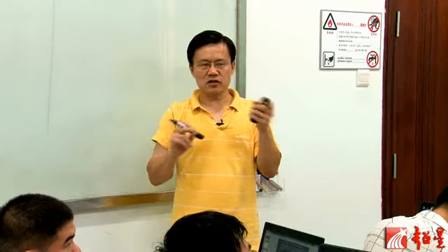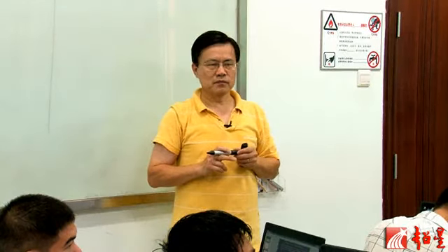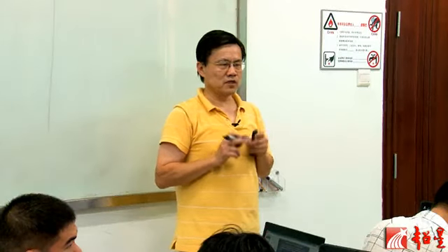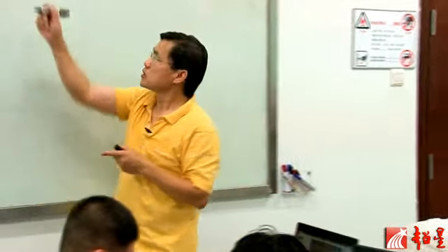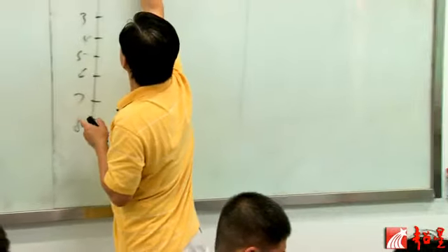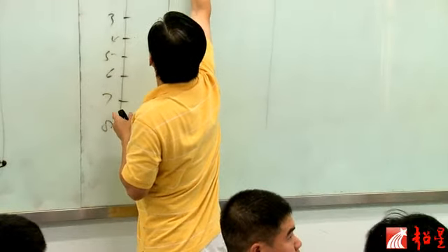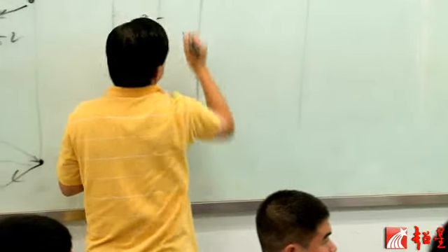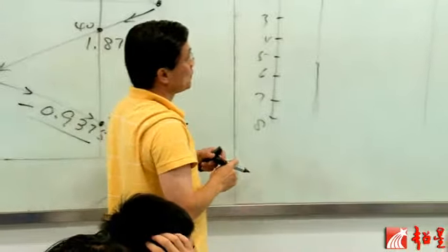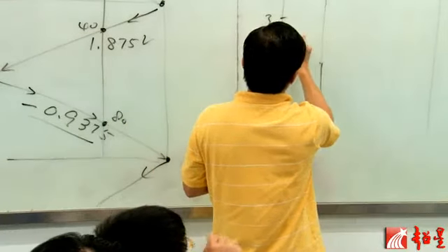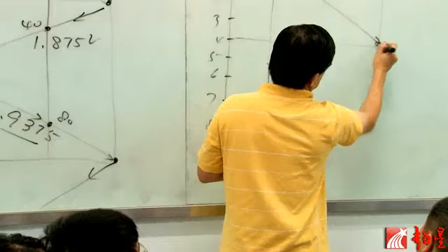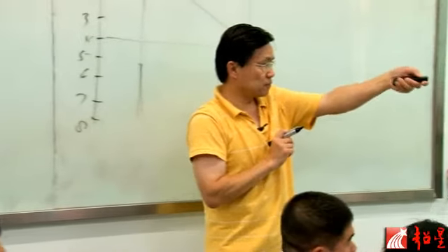One-third, right? Positive or negative? It's negative 1/3, right? So the reflection coefficient here in the middle is negative 1/3. So negative 1/3 of this voltage is going to be reflected. The rest will continue to go towards this first load there.